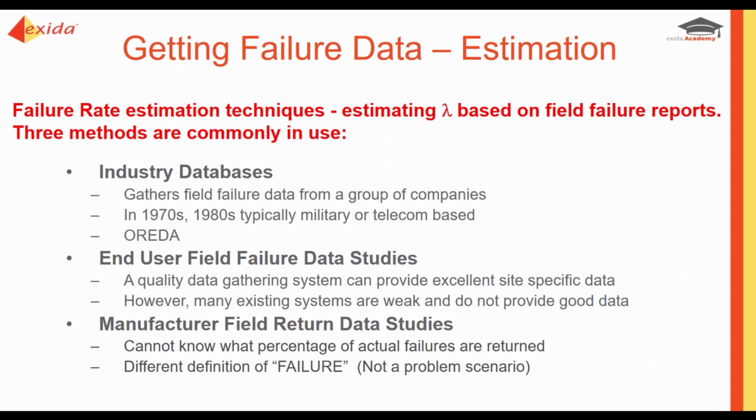The great thing about industry databases is this is real information. These are real failures, and depending on how it is documented, this could give you a wealth of knowledge. If you just have a, yes, we had one failure, it's not going to give you so much information. However, if you're doing as found conditions, this could be very useful. However, make sure you are using an apples to apples comparison. If you are a nuclear plant, you might not have the most relevant information in the offshore North Sea handbook.